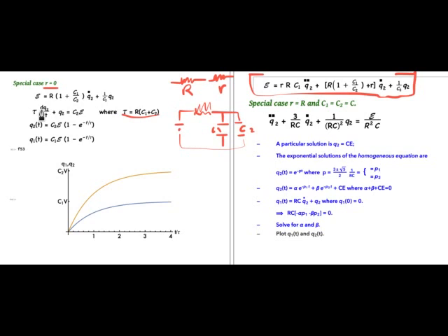Now multiply both sides of the equation by C2. So on the left-hand side, I'll have C2 times the EMF. On the right-hand side of the equation, I'll have R times (C1 plus C2) Q2 dot. That's tau Q2 dot, so that's over here. And I multiply the equation through by C2, so this last term will just be Q2.